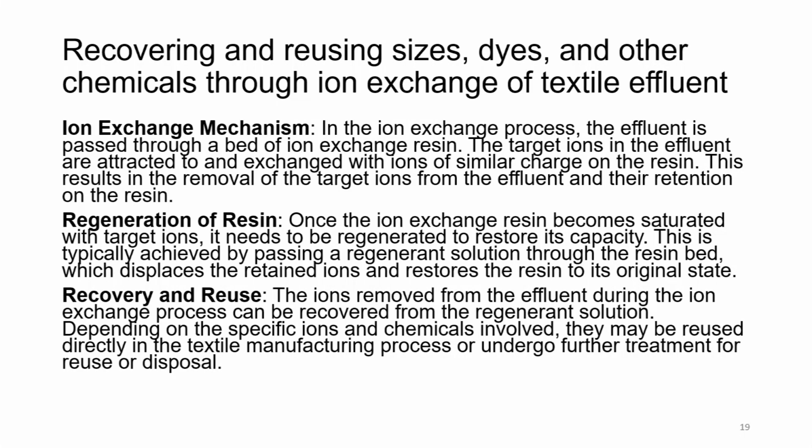Regeneration of resin. Once the ion exchange resin becomes saturated with target ions, it needs to be regenerated to restore its capacity. This is typically achieved by passing a regenerant solution through the resin bed, which displaces the retained ions and restores the resin to its original state.